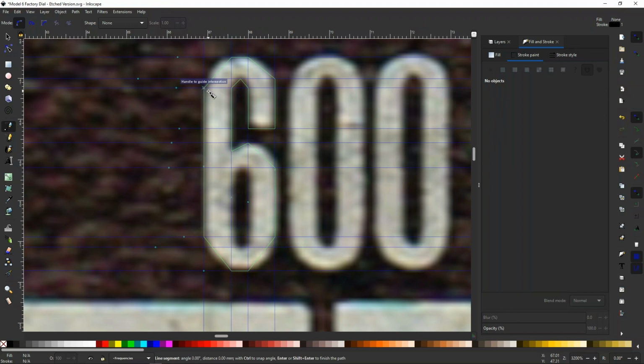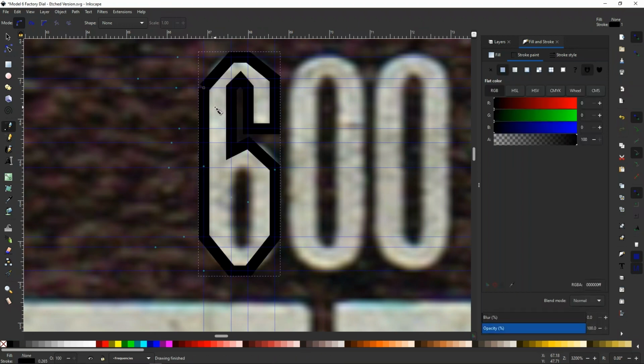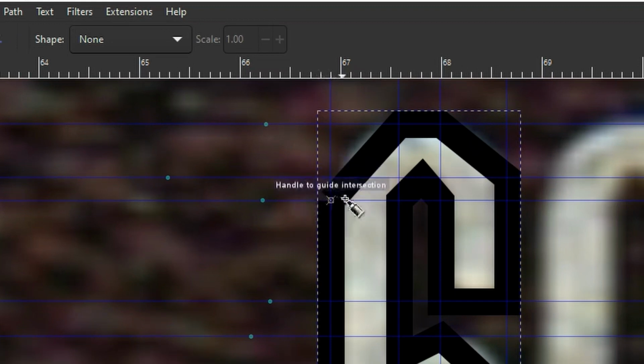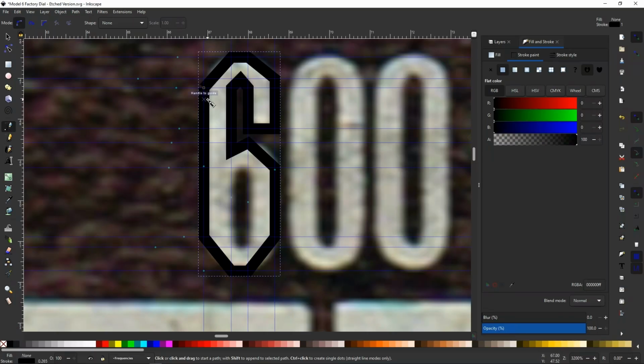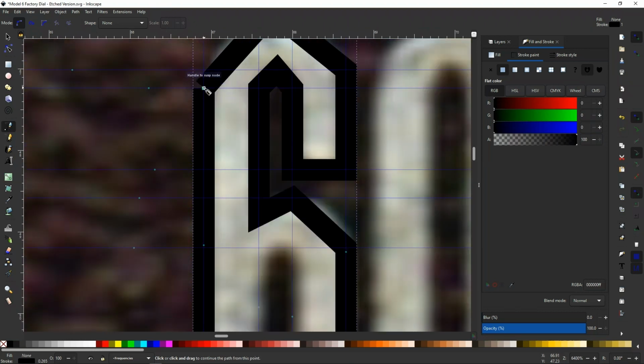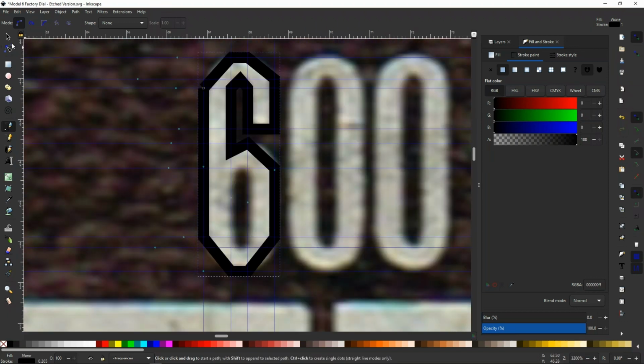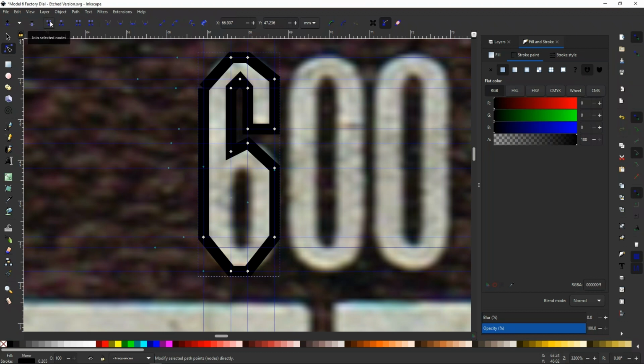And close it out. Now to finish a Bezier, hit enter, and here you'll see that this hasn't closed the loop. You can see that the line here ends and the starting line ends. So let's just go to our node select tool. There are two nodes there, the starting node and the end node. They're stacked on top of each other. By dragging a box around them, we select them both and then join the selected nodes, and watch what happens. Boom, we now have a closed loop, and that's what we were after.